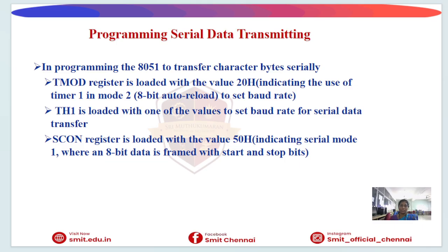Then the SCON register is loaded with 50H. This configures the serial port in mode 1. In this mode, the 8051 transfers 8-bit data with one start bit and one stop bit. It also enables the serial reception. These settings prepare the 8051 for serial communication.